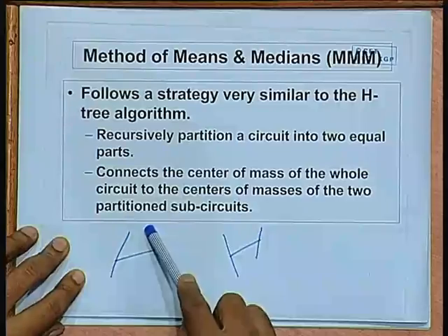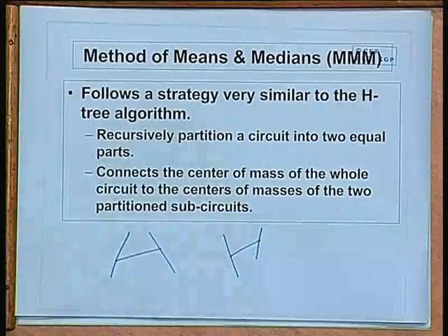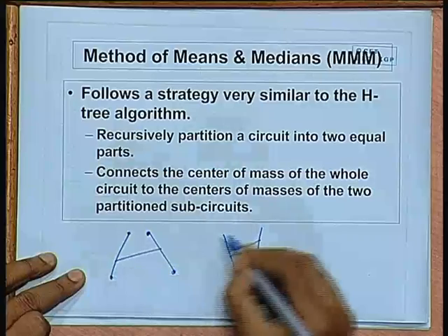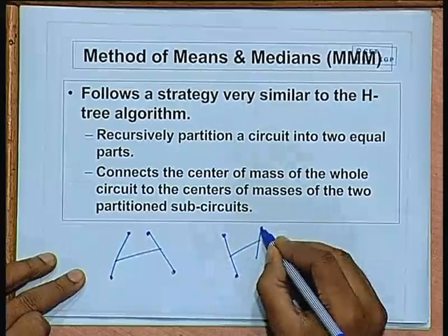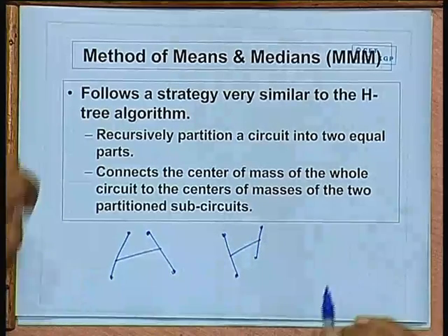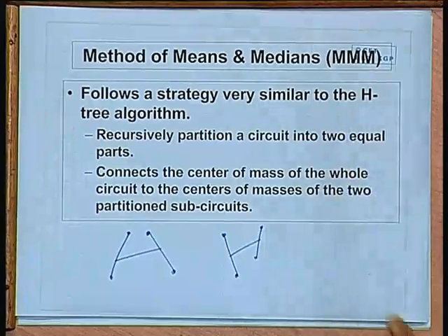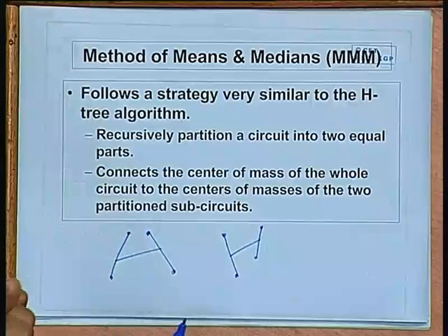So, you are making these adjustments depending on which are the points you need to distribute the clock net to. In concept, this is similar to the H-tree algorithm, because your whole interconnection network will look like an H-tree network, but with zigzag kind of lines. These will not be rectilinear lines again.